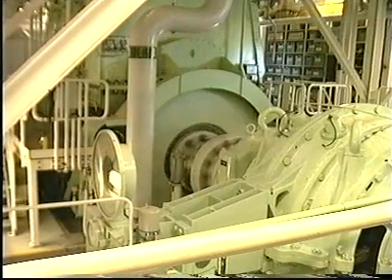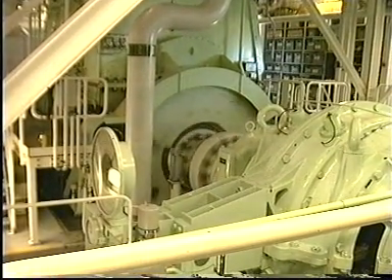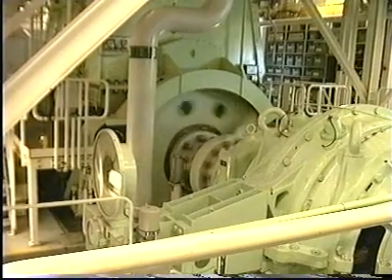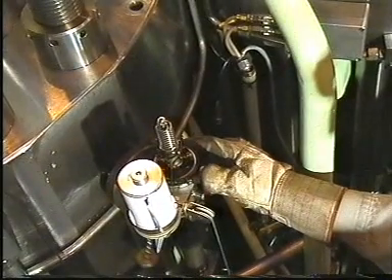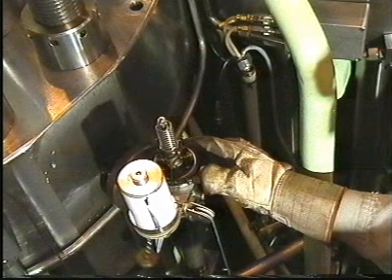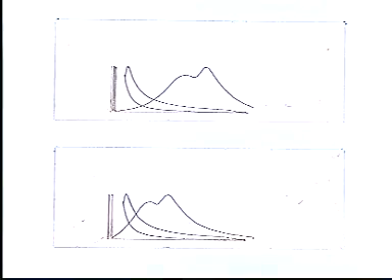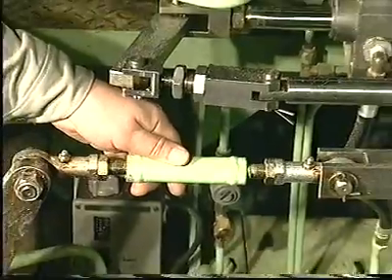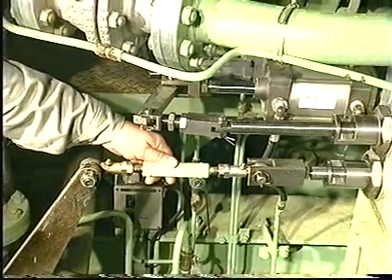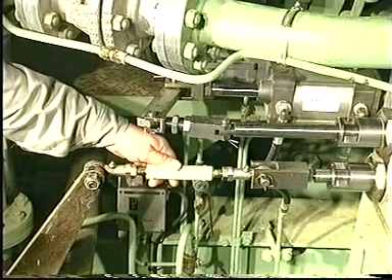Start the engine and run it up to a load corresponding to the break point load, and thereafter to 100% MCR load. Use the indicator drive or PMI system to adjust the load so that it corresponds to the breakpoint load and 100% MCR load. Note down the fuel pump indexes. The mean indicated pressure of the individual cylinders must not deviate more than 0.5 bar. If the deviation is larger than 0.5 bar, adjust the load distribution on the fuel index rack of the individual cylinders.